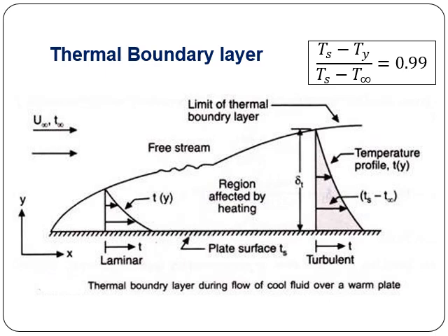At a certain location of x, at the plate surface the temperature difference is maximum. That means if you take the difference between the surface temperature and the fluid, it is maximum at the surface, but as you move away from the surface, the fluid which is passing over the surface will gain heat and get heated up. So this difference will go on decreasing and the layers will get heated.